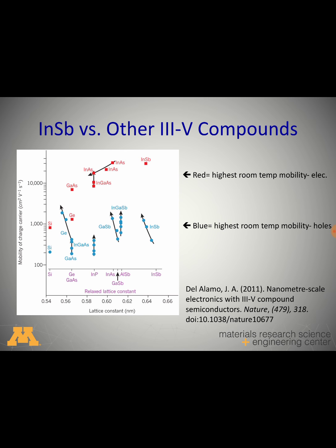And we can see here on the left a nice comparison between indium antimonide and some other 3-5 materials. Here on the far left we can see silicon, which is a commonly used semiconductor material in solid state research. We can grow nanowires using silicon, and we can see that it has an electron mobility rate of less than 1,000 square centimeters per volt second.